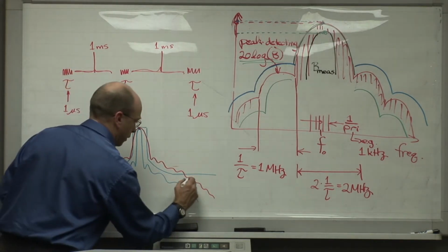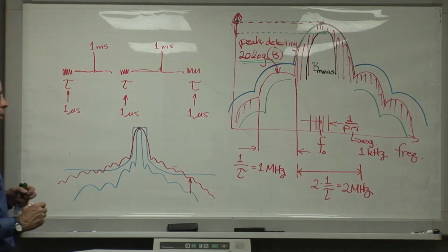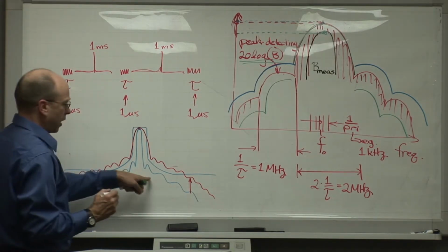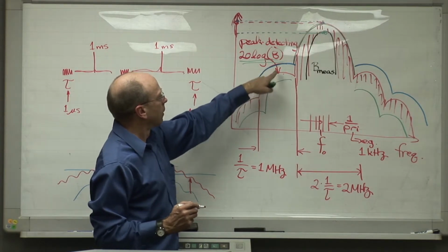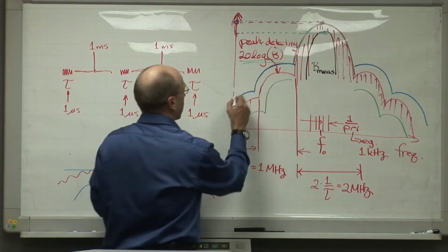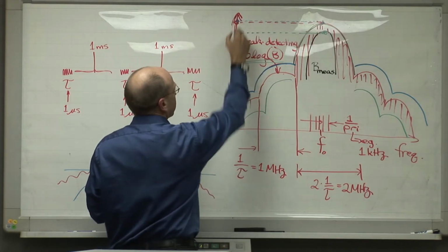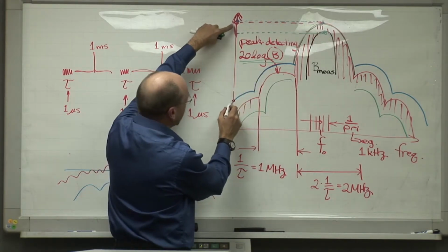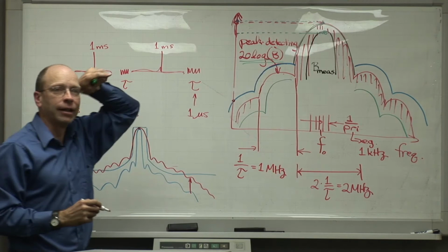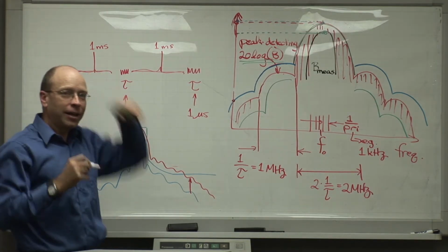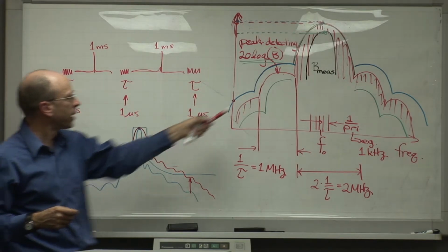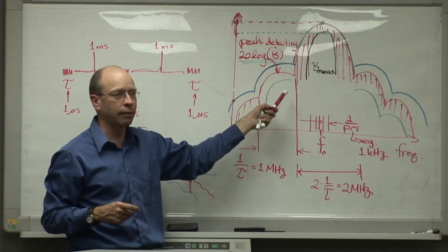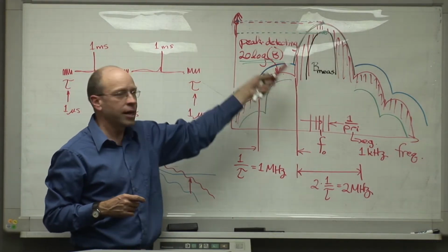And where, in other words, there's an offset in power. If I go to this wider bandwidth relative to this more narrow bandwidth, the offset in power at some frequency out here relative to the fundamental changes as a function of the bandwidth that I'm measuring in. So there is no single emission spectrum that the radar produces in terms of the way that we have to measure it. We have to measure it with some bandwidth, and we're getting a variation in here.